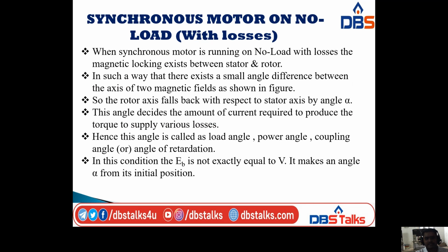Next, coming to the synchronous motor on no load with losses. In the previous case we discussed the synchronous motor on no load without losses, but now I am discussing the synchronous motor on no load with losses. When it runs on no load with losses, the magnetic locking exists between stator and rotor in such a way that there is a small angle difference between the axes of the two magnetic fields.